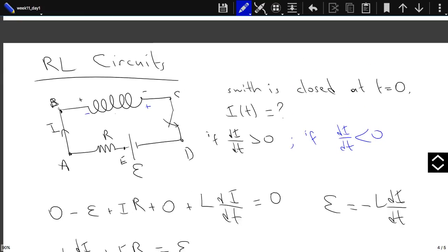And as I said, even if you don't put an additional inductor in your circuit, if it has a finite area, it itself has a finite inductance. Because if you run a current through your circuit, it will create a magnetic field, and if the current is changing, the magnetic field will be changing. That will create a changing magnetic flux, and it will create an EMF that will oppose the change, even if you don't put in an additional circuit element. That makes it difficult to construct circuits whose currents should be changing fast. For example, in your CPUs, they have their clock. What that basically means is that the current should be changing its direction at whatever the clock speed is.